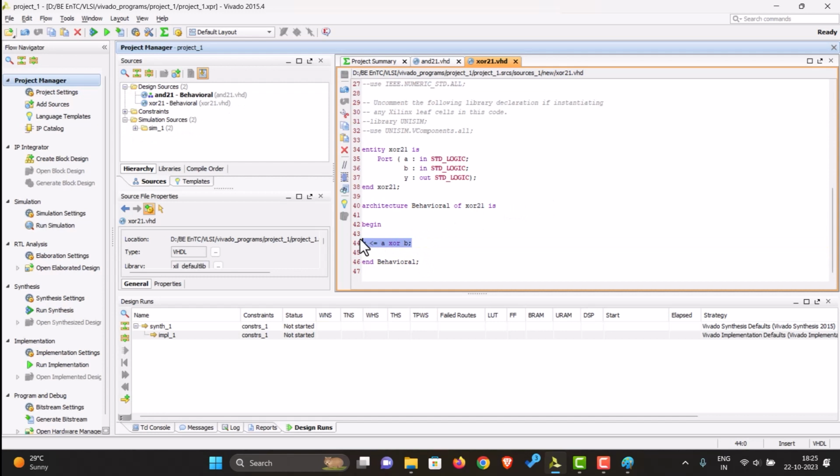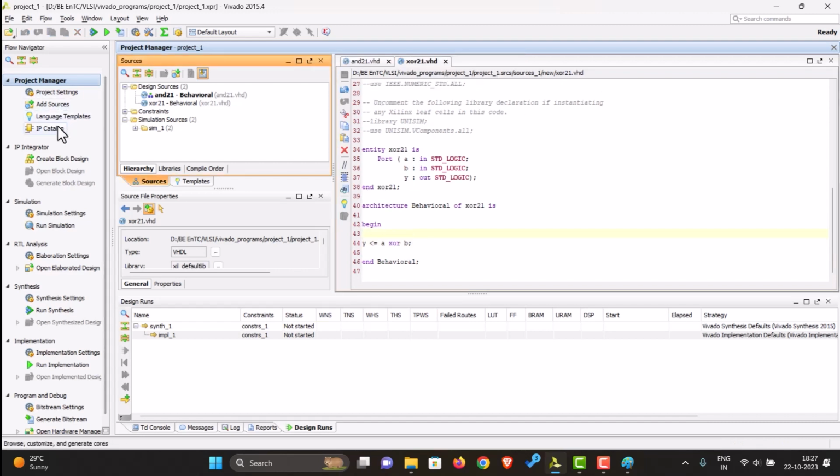This isn't actually very complex, but we have to make this because we have to make the half adder using structural style of modeling. If that wasn't the case, we could have just used these equations in the half adder code itself. But now, as the XOR gate and the AND gate are ready, let's also create the half adder.